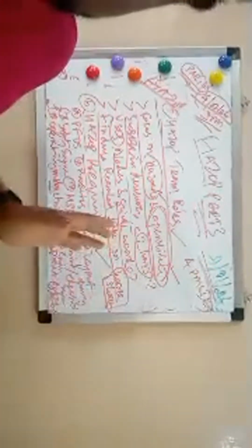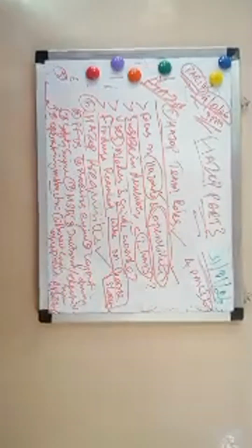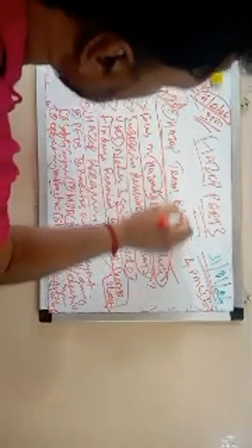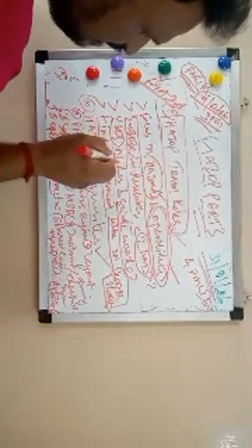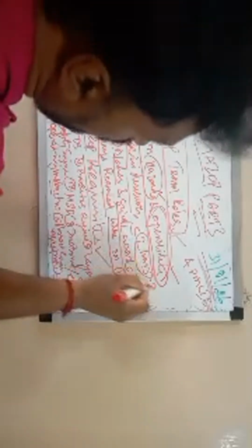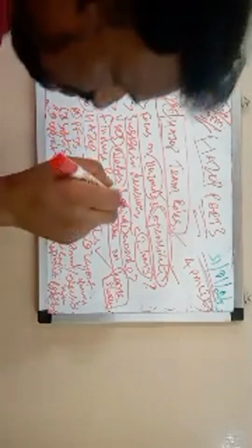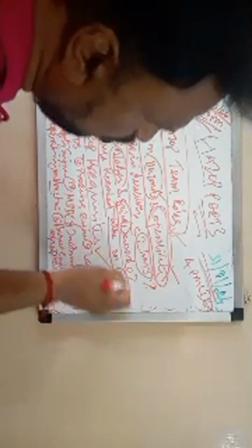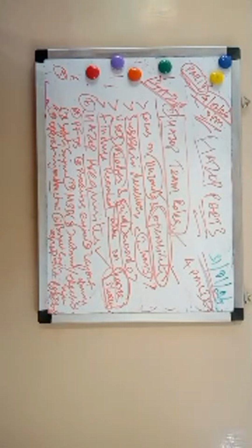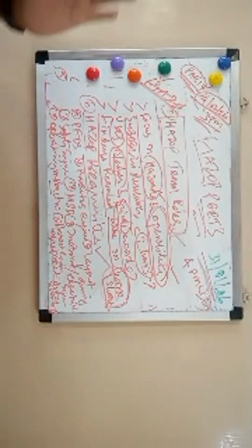All these people together do the HAZOP study. So for the HAZOP team roles, you have to know: focus on hazards and operability, session less than 2 hours, using the notes and guide words, and findings always recorded live on worksheets. So this is one part, the team roles.